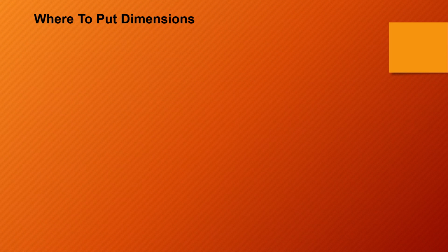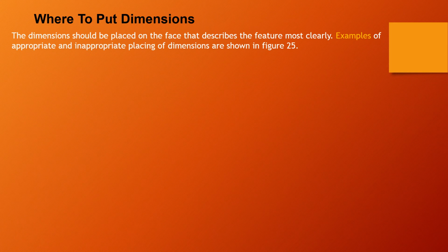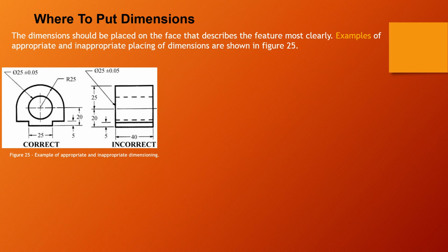Where to put dimensions? The dimension should be placed on the face that describes the feature most clearly. Examples of appropriate and inappropriate placing of dimensions are shown in figure 25. You can see it here.